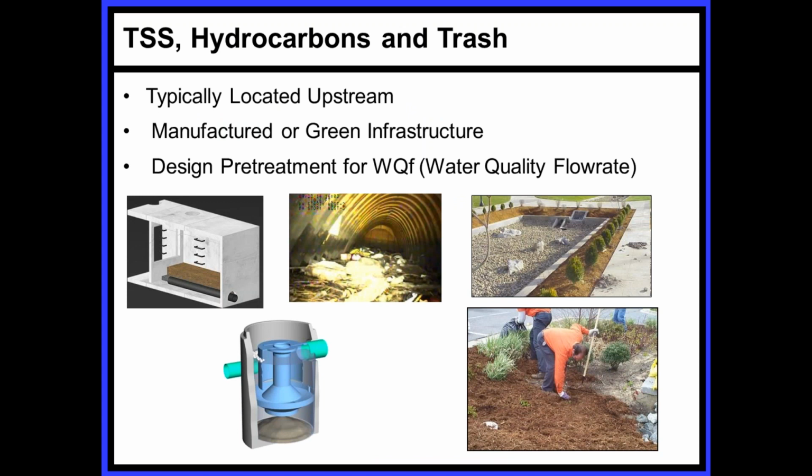Bioretention and pervious pavements, they are treatment methods. They are not good at trash. They are generally not good in bioretention if you're on sites that have hydrocarbons, but they do a good job of filtering suspended solids, phosphorus, nitrogen, other contaminants such as that. Subsurface technologies are broad as well. There are a host of hydrodynamic separators that are decent at removing sediment and oils and trash. The chambers themselves, as I showed earlier, are very good for sediment, but they can also store trash and other contaminants that are flowing off of a site. Sand filters and other boxes are also methods that can be utilized.